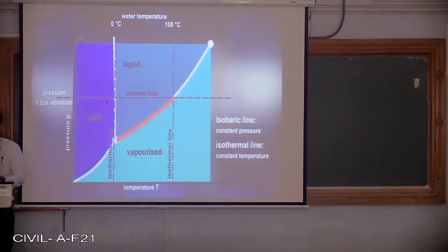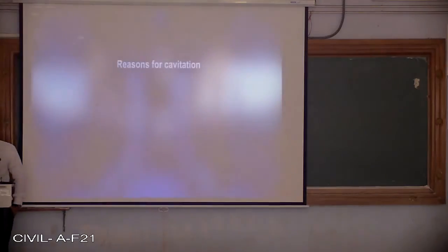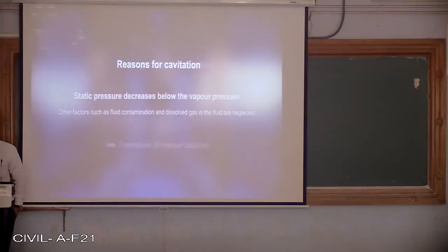Water can vaporize below 100 degrees Celsius if the static pressure is low enough. This is exactly what happens when cavitation occurs. Bubbles of water vapor form when the pressure in a certain location decreases below the vapor pressure.